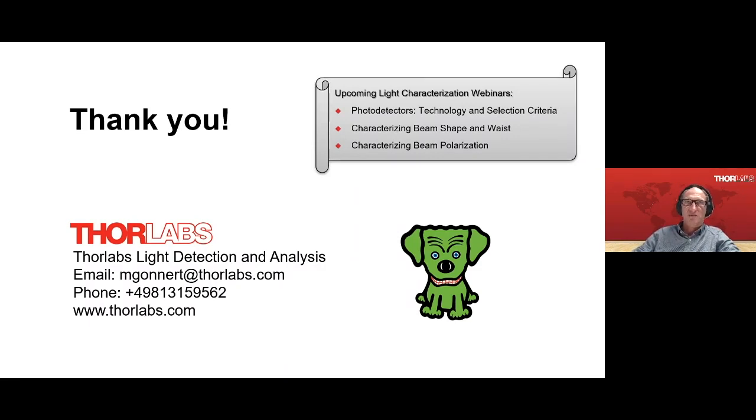For thermal sensors, you use a laser to calibrate. This is mostly sufficient to do at one wavelength, since then you know the absorption of the absorber layer material. When you really want a specific wavelength, then you don't rely on the absorption; the calibration can also be done at other wavelengths, which gives a better result. Really important for both calibrations is to have a reference standard that has been calibrated at an external national body like NIST, or here in Germany the PTB.